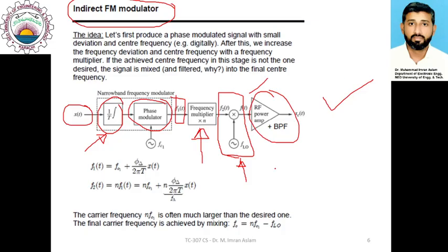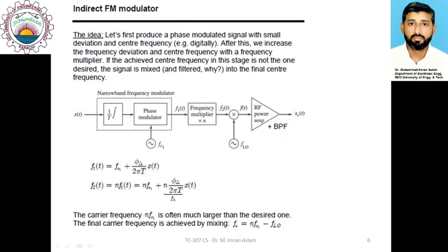For this case, if we look at this f1 signal, which is the phase modulated signal, it would be represented by this. It will have a constant factor of t, and this phi delta represents the maximum phase deviation when it passes through the frequency multiplier. You would see that the overall frequency would be multiplied by this factor n, because we have used the multiplication factor of n.